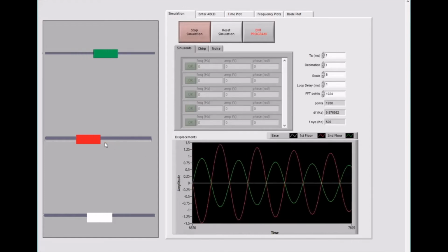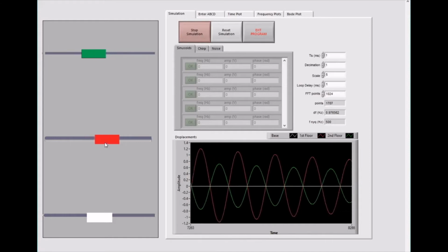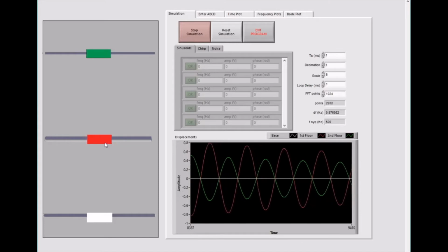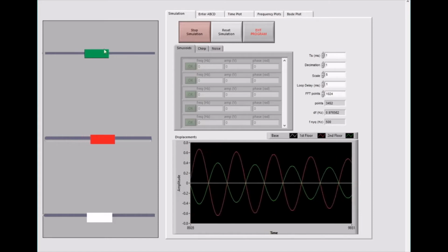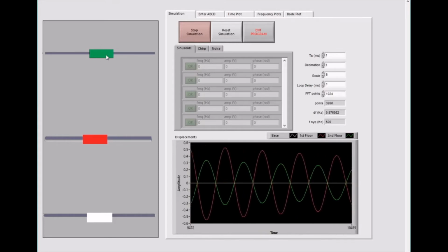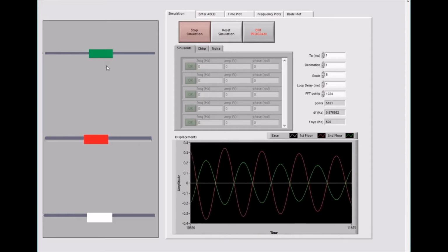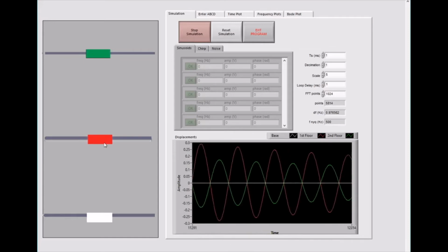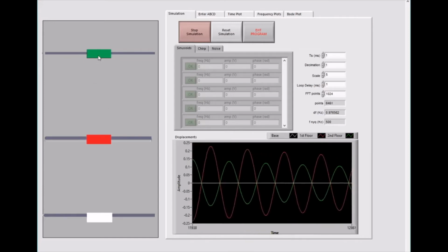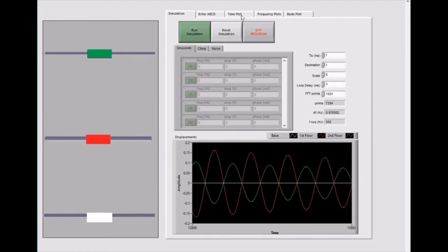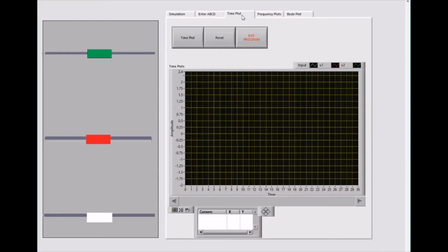What do you see? The first floor has bigger amplitude. When this is 1.618, the second floor has an amplitude of 1, and they're 180 degrees out of phase. When mass 1 is at its maximum, mass 2 is at its negative maximum, or the minimum. And another thing, it's a pure sinusoidal function. It has only one frequency, and you want to see what the frequency is.